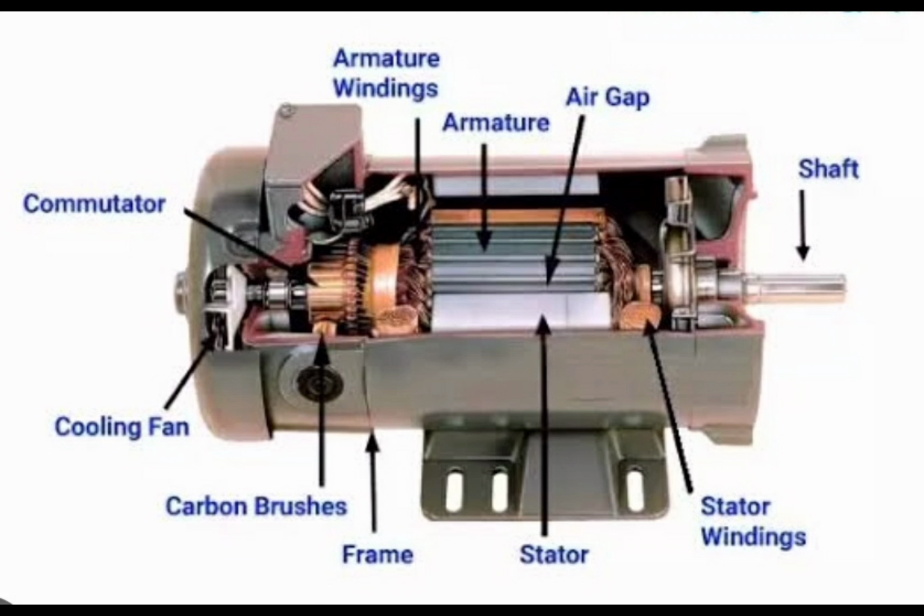A stationary part like a stator is one of the parts in the DC motor, which includes the field windings. The main function of this is to get the supply. Next component, rotor. The rotor is the dynamic part of the motor. It is used to create the mechanical revolutions of the unit. Next one, brushes. Brushes using a commutator mainly work as a bridge to connect the stationary electrical circuit to the rotor. Next one, commutator. It is a split ring that is designed with copper segments.